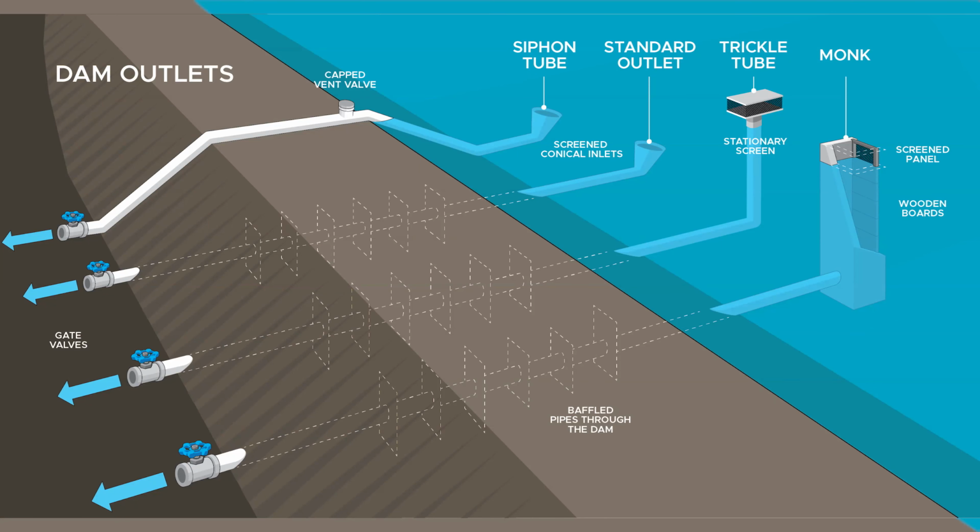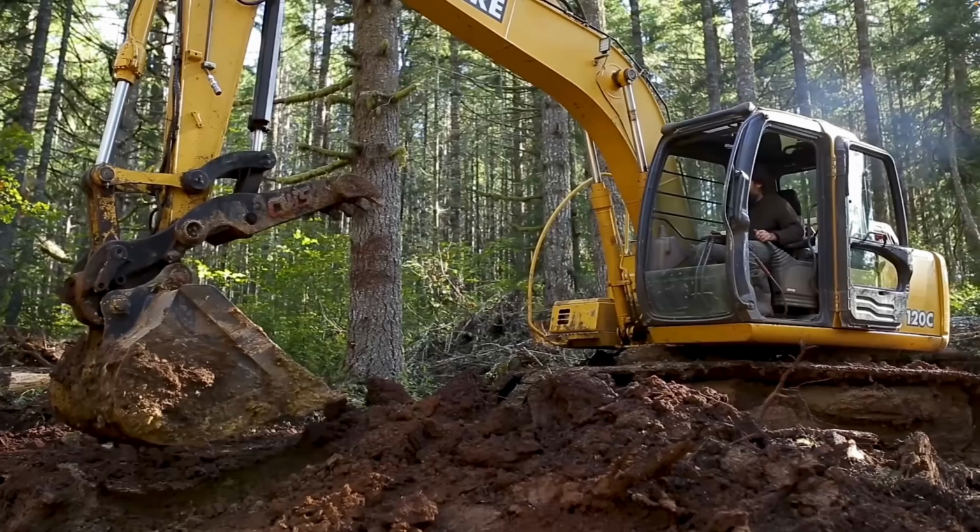The valves can go on the inside, within the pond, or outside, and it's really a matter of preference, but most people put the valve on the outside of the dam because it's more accessible and it's not exposed to water. The outside valve can take more pressure, so it can end up being more leaky, but the inside valve, being exposed to water, can degrade quicker. It's a little bit more challenging to maintain and to service.